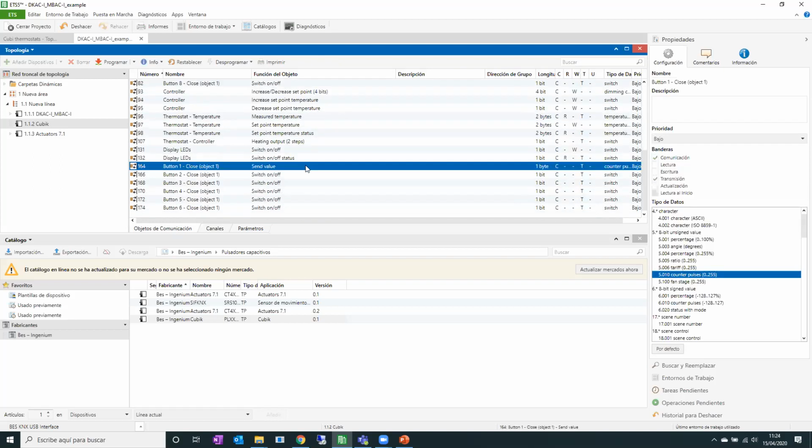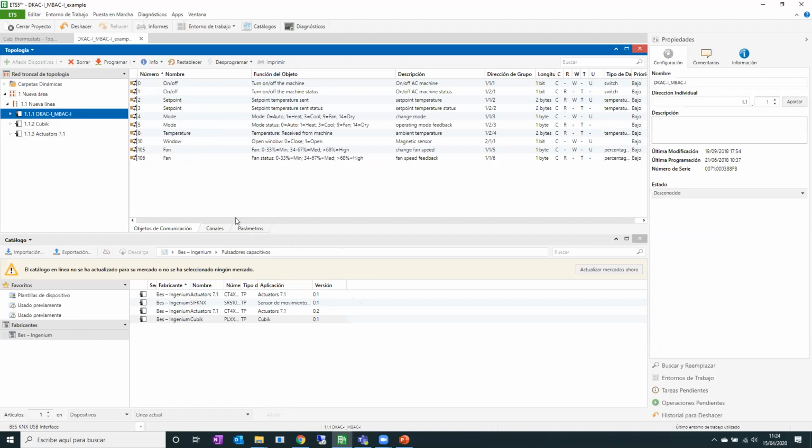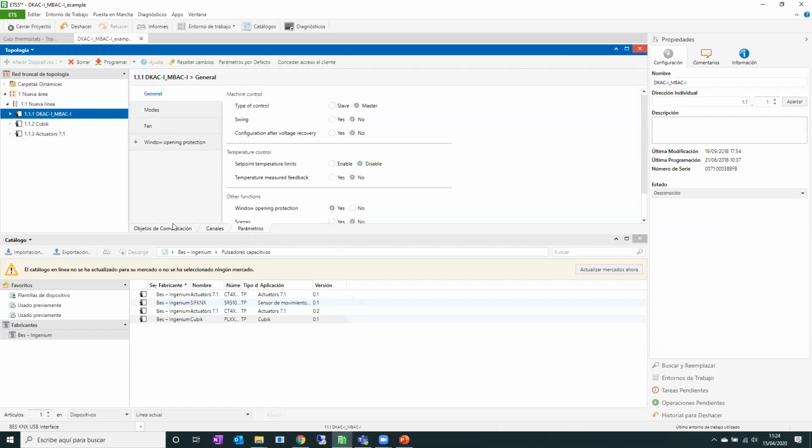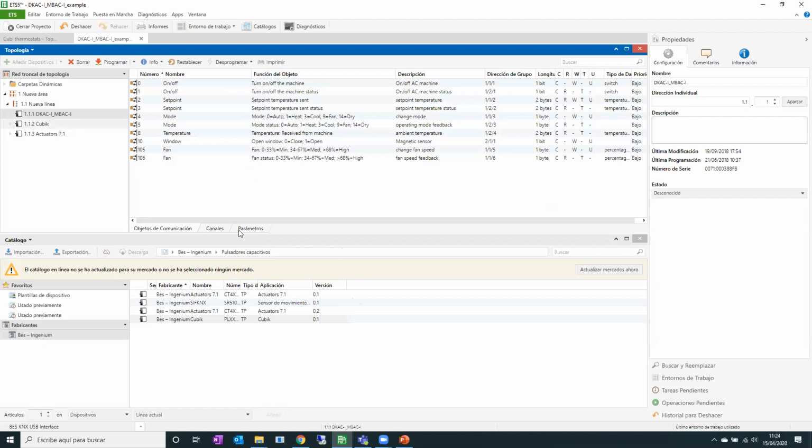Okay, I understand. I had a misunderstanding about the thermostat. Some thermostats from other manufacturers fix the function of the button, but your products can change the function. Yeah, you can change all the functions of the buttons. You can change the telegrams that the buttons send. So depending on the telegram that you select, you can control different things. So with a button, you can send many different telegrams.